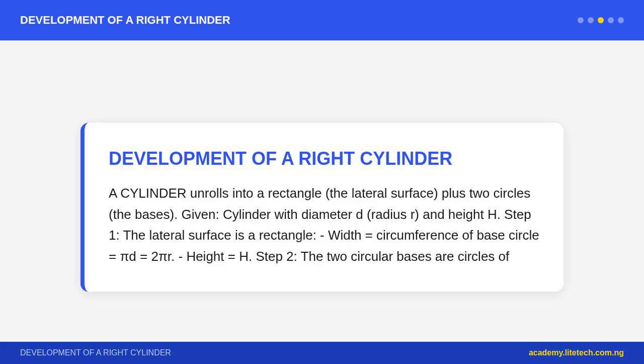Question 1. What is the development of a surface and what is its practical use? Answer. Development of a surface, pattern development, is the process of unfolding the outer surface of a 3D solid into a flat 2D shape. It is used in sheet metal fabrication, packaging, and ducting to determine the flat pattern that, when cut out and folded or rolled, produces the required 3D shape. Applications include manufacturing tin cans, ventilation ducts, cardboard boxes, funnels, and pipe fittings.